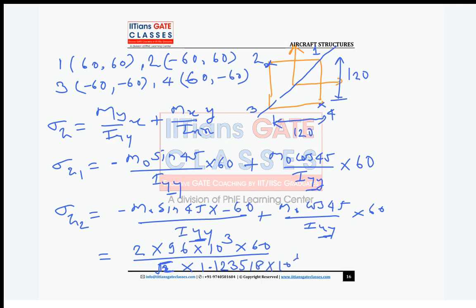So from here you will get your stress in what? Megapascal. It is in Newton per mm square. No, Vijay, you are wrong. You are getting 7 point, guys. Are you getting 7.25 Newton per mm square, right? So 1 Newton per mm square is what? 1 megapascal.